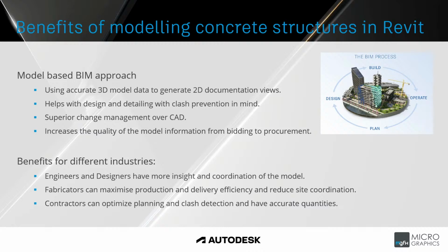From them, you generate your 2D sections and elevations without redrawing anything. And if you change the 3D model, then your 2D information adjusts, be it sizes or shape, that sort of thing. Right, and that also helps with clash detection when you're modeling rebar within these models.